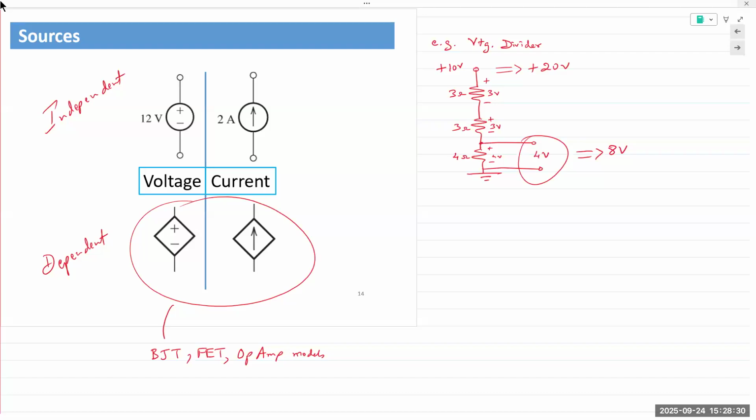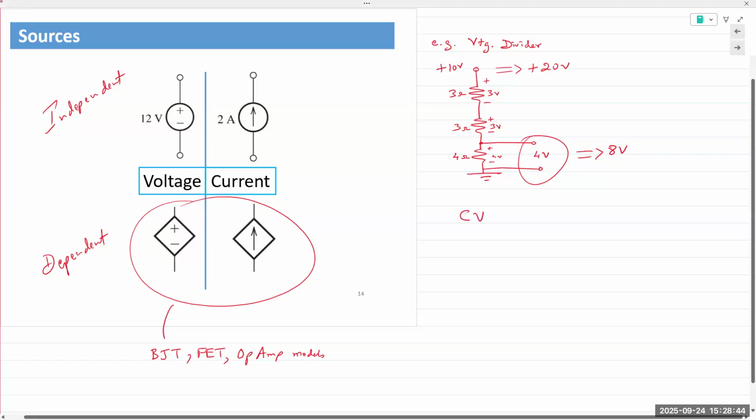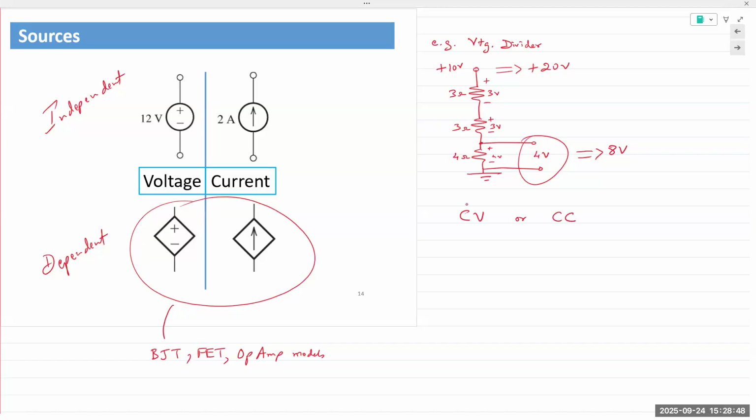So next time you're in the lab, if you're in my lab, I'll point it out. But next time you're in any lab and you turn on the DC power supply, you look at the top of the screen, somewhere there will be a CV or a CC. Constant current mode is not something we use. Very rarely do we use that. Most experiments will run in CV mode.